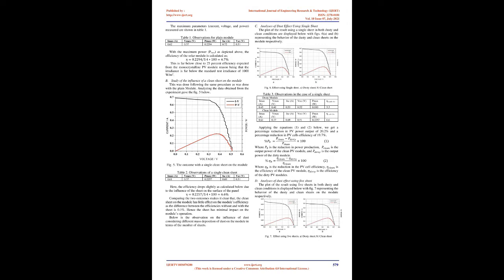The samples were air-dried and sieved through a 2 mm sieve. The samples were then weighed and adequately mixed. On Thursday, July 13, 2017, the soil was poured into 2 liters of water in a container and left for 4 days for the soil to soften up to have a finer quality, where it was then filtered.